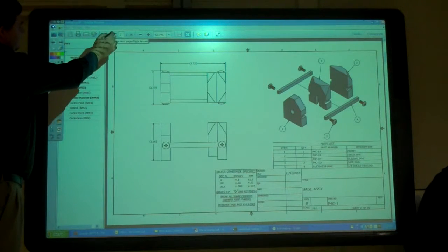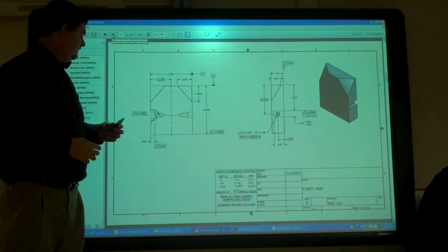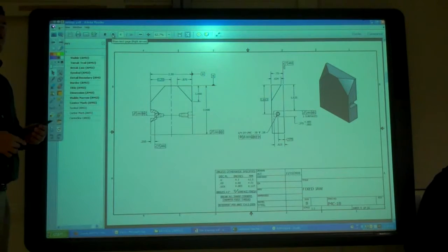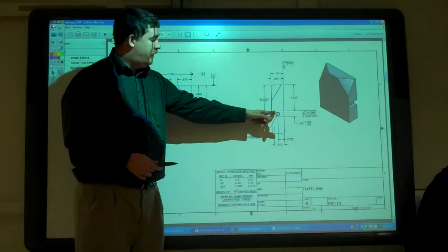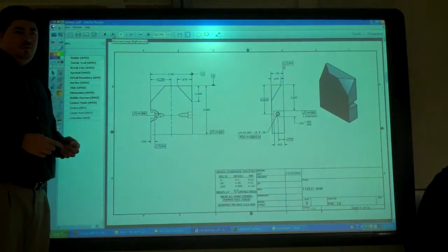It's pretty tight fit. It is. But I'm just saying it all depends, right, on the part. If the tolerance is forgiving, then you could always leave a little bit of a radius there. And you could also put a smaller radius, and that'd be easier to do on the other part also.